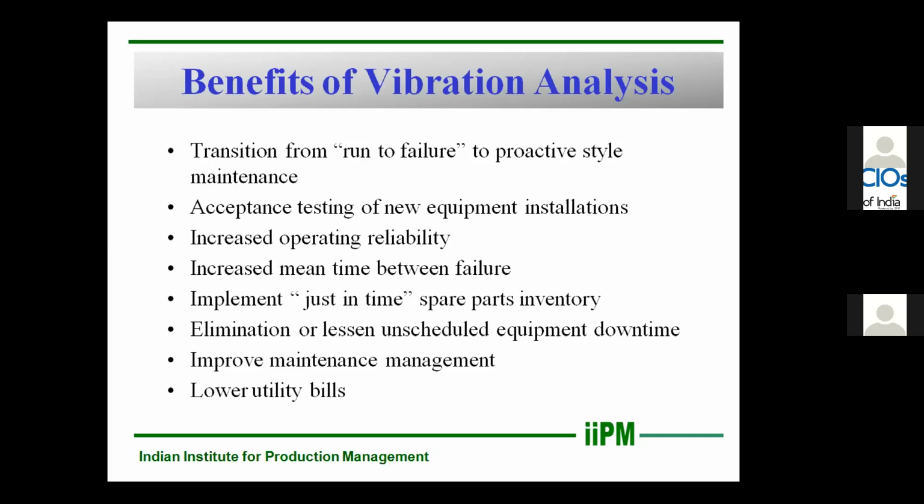And then increase mean time between failure. So what is MTBF? It is the average length of time between one failure and another for a component, or we can say it is the reciprocal of failure rate. Then implement just in time spare part inventory, because if we are doing vibration analysis at the right time, we can have our stock or inventory in the scheduled time. We need not procure or wait for the spare parts to come, then we can replace. So it helps in just in time spare inventory.